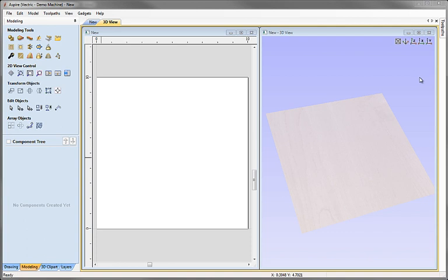We also have ways to export our data as different file formats. Typically in Aspire, the end result is to take your 3D models and your vectors and create toolpaths with them and output those to the CNC. In some cases though, you may want to save your 3D data. One application, as we've already seen, is to save the files in native Aspire format so that you can import them back into the software and use them as pieces of clipart in other designs.